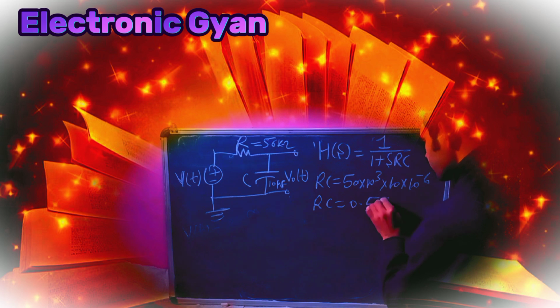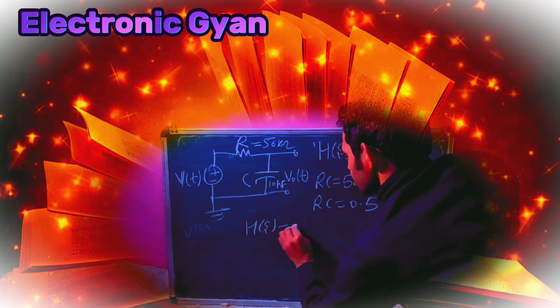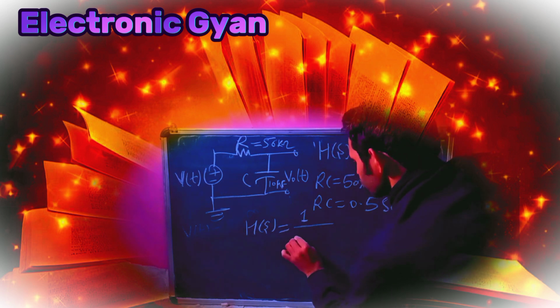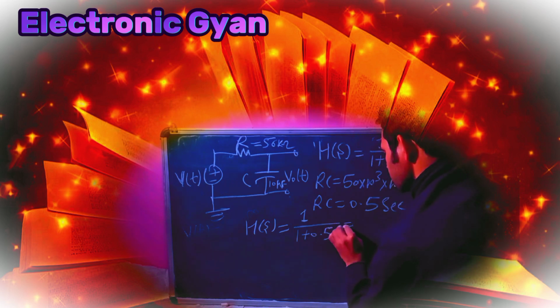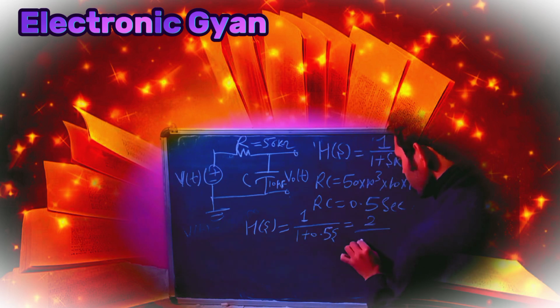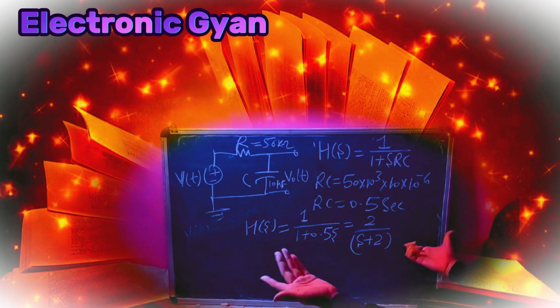This is nothing but 0.5 second, the RC time constant. Therefore my transfer function will be 1 by 1 plus 0.5s, which is nothing but 2 divided by s plus 2. So this is the transfer function that we have obtained.